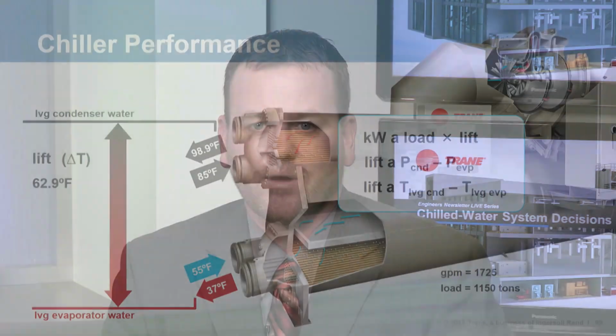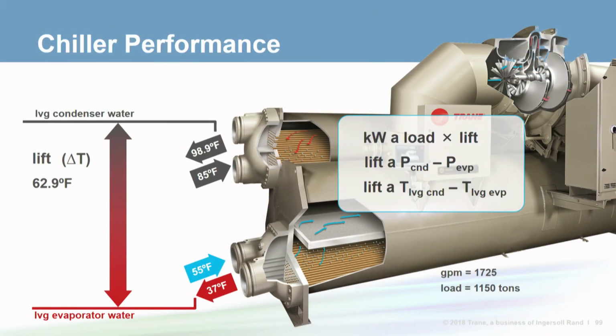Before we do this, let's revisit the fundamentals of chiller performance. There are two factors that impact chiller performance. The first is the amount of load the chiller has to satisfy, and the second is the lift a compressor must generate. The amount of lift is the difference in refrigerant pressure between the evaporator and condenser. The refrigerant pressures are proportional to the temperature of the refrigerant. Therefore, the colder the evaporator and the hotter the condenser refrigerant is, the higher the lift. Finally, the chiller kW is proportional to the amount of load and lift. If one can reduce the lift, the chiller kW will also come down.